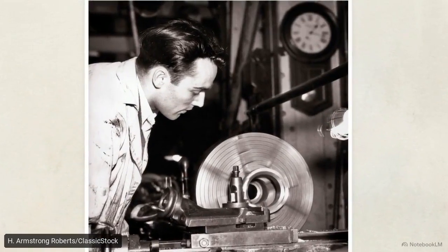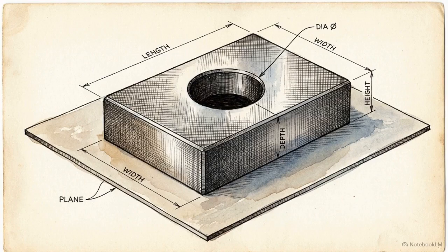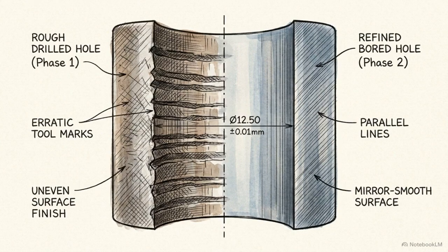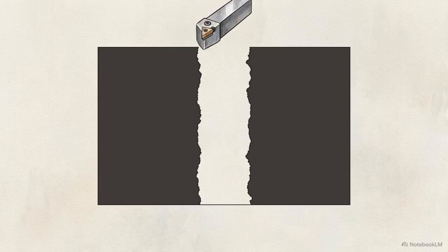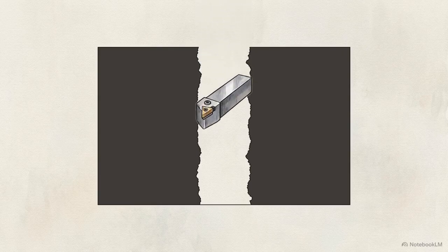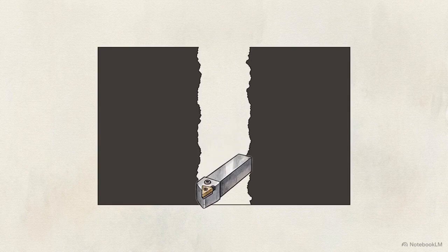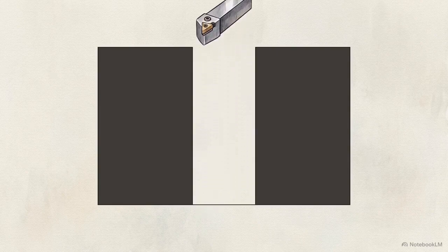the outer diameter. When it comes to making internal holes, there is a strict functional difference between creating the initial void and refining it. This diagram outlines drilling, plunging a bit down into metal to create a hole, leaving a rough inner wall. We correct that through boring. A single point tool travels down that drilled hole, shaving a microscopic layer to achieve a perfectly precise diameter.